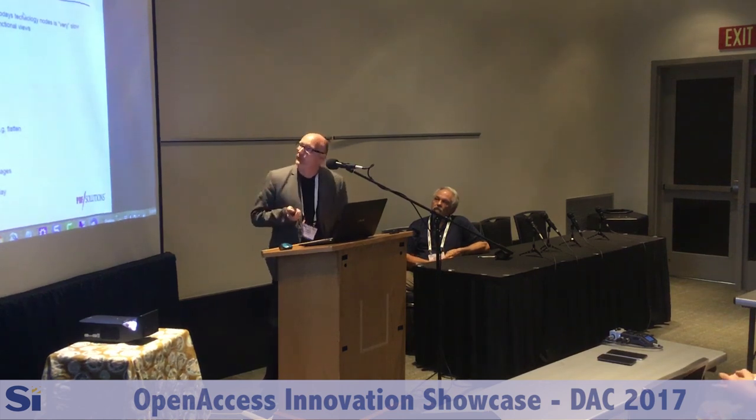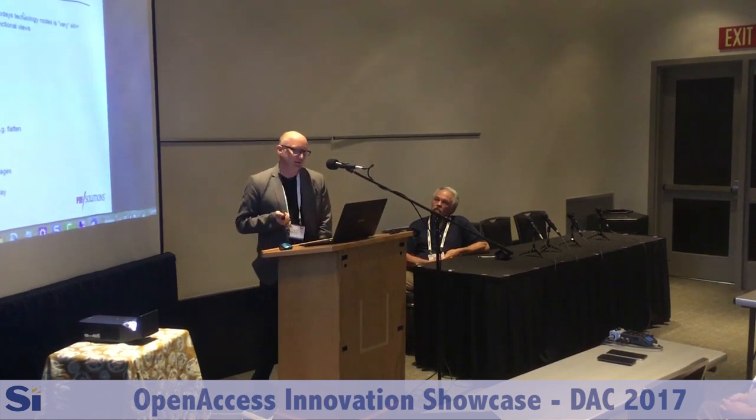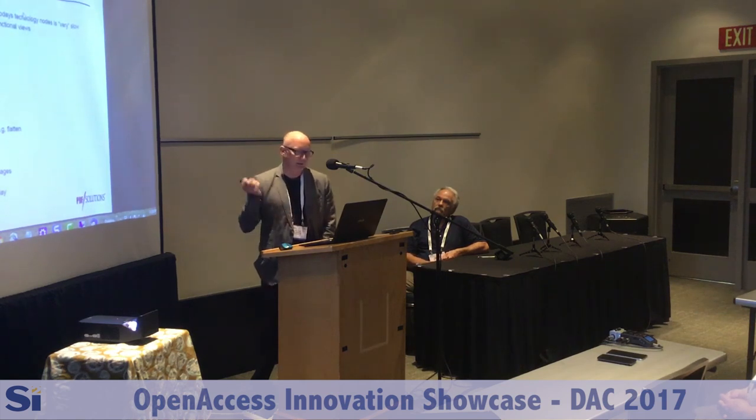So some outlooks, some limitations, future work, and final conclusions. Full chip layouts, as I mentioned: opening a design, for instance, at 7 nanometer is incredibly slow, especially at a full chip level, because the time it takes for something like Cadence to go through all the hierarchy levels and parse everything is just incredibly slow. I tell everyone I have designs where it takes 2 hours to open a cell, so I go to lunch, and when I come back, it's maybe open. So we need smarter ways of looking at layouts.